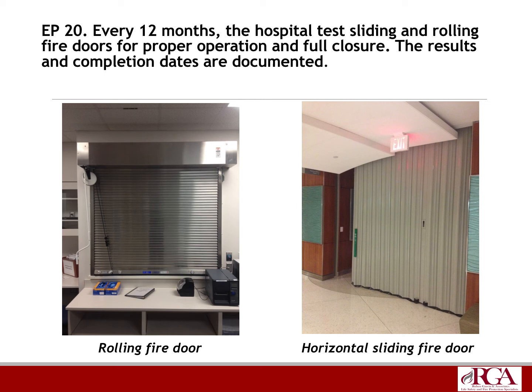Sometimes if you're in an older institution, you'll have a big rolling fire door. To me, that's dangerous because once it rolls down, it will not allow egress. The benefit of these horizontal sliding fire doors by one door is that you don't even know they're there until they come out, first of all. Secondly, it allows egress by way of this push to exit hardware that's on here.